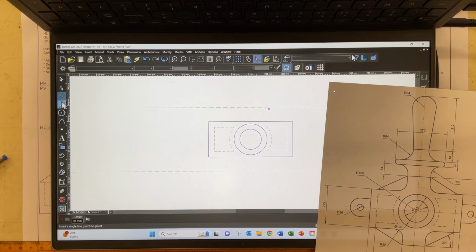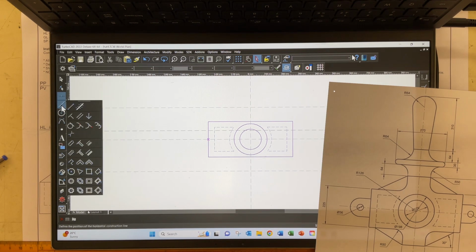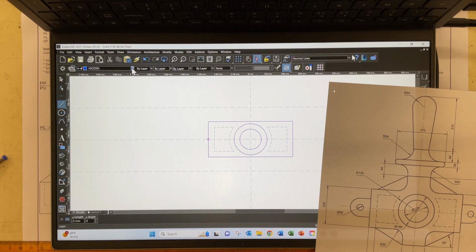I haven't drawn any center lines in, let's just do that quickly. I'm going to take a vertical construction line. I go to the center. Now I've got the snap option that it goes to the center of that line, and straight away I've got a line going in the center. Do the horizontal one, and again you can see how it's snapping to the center of that line over there. Once I've got that in place, pop in some center lines. It's always a good idea.